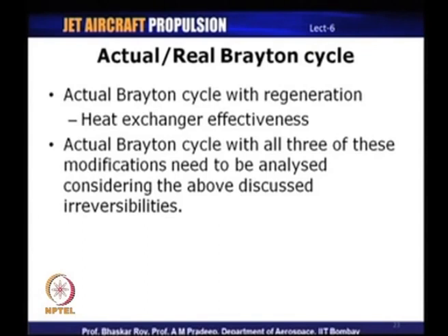So, an actual Brayton cycle with all these three modifications will have to be analyzed while considering all these irreversibilities, which pertain to efficiencies of the compression process and efficiencies of the expansion process, and also pressure losses taking place during either heat addition or heat removal or during the reheat process.